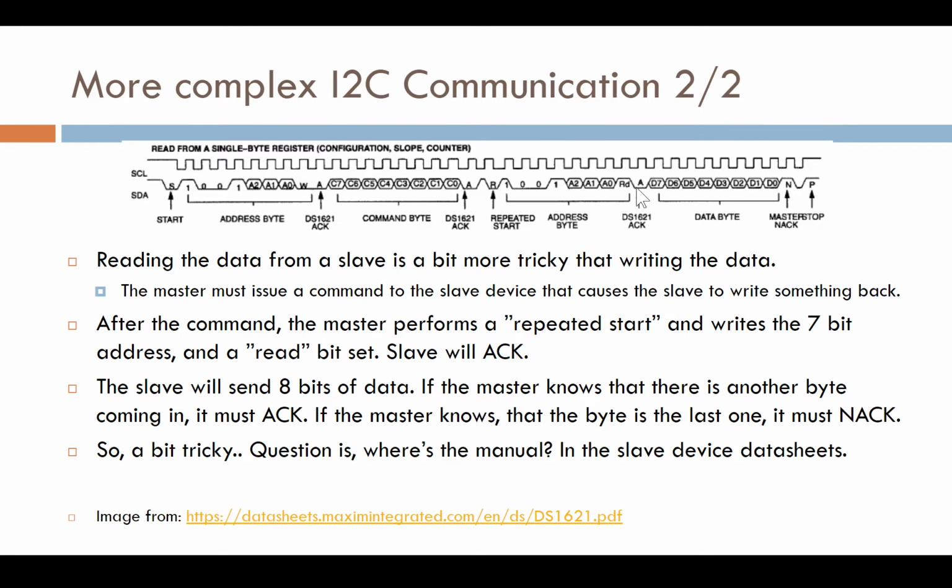And this acknowledgement is set by the device, saying, okay, I'm here. And then the data byte is given by this device, and the master, meaning the processor, gives the acknowledgement signal. In this case, it's a 1 byte transmission, not acknowledged. NACK actually means the end of transmission. And then stop. Okay, tricky. So it's a bit tricky, yes.